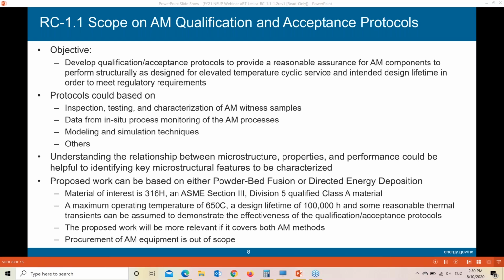As I've said, if you look at the material in the so-called virgin state, for example, if you have the grain size, you have the defect structures, you make the EBSD map, et cetera, whether or not that will help us know that the fatigue performance in 10 years will be what the designers have counted on is difficult.